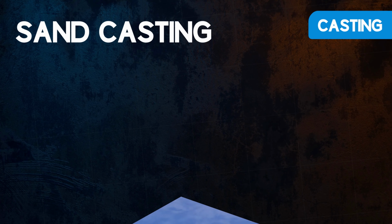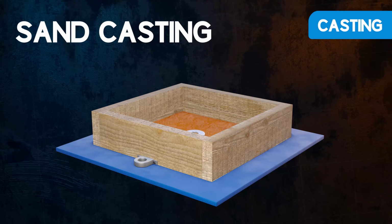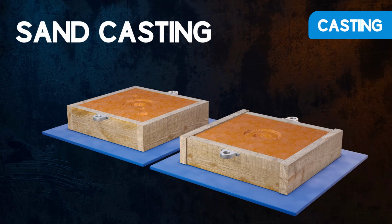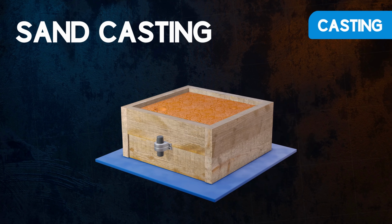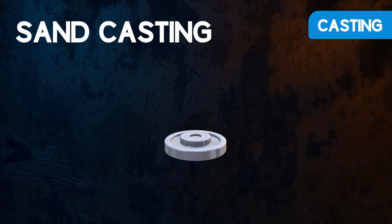In sand casting, a pattern is used to create a single-use mold from damp sand. The sand is typically contained in 2 mold boxes called the cope and the drag. Molten metal is poured into the mold through a channel formed in the sand. When the metal has solidified, the cast object can be removed from the sand.